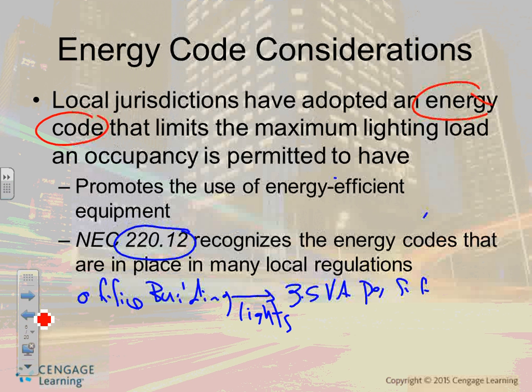And number three, these will not meet the energy code, because if you guys left the room, the light will stay on for a long time. So what meets the energy code is an occupancy sensor, they call it. Now it's called a vacancy sensor. They put it right in there, guys. You walk in, it hears and sees you. Most of them are dual technology. They can hear and see you, literally. So they send all these waves that can hear and see you. So if you're in the area, even typing will keep the light on.